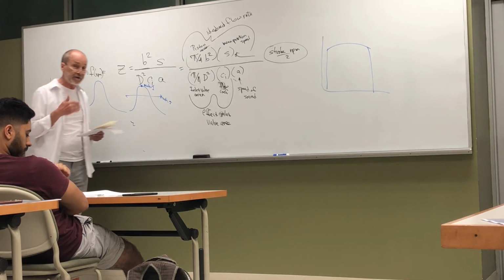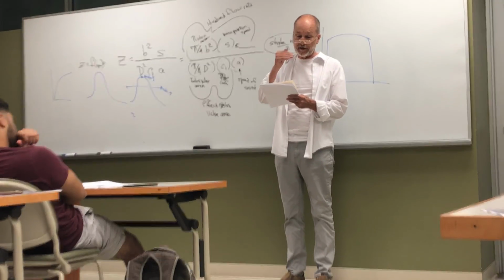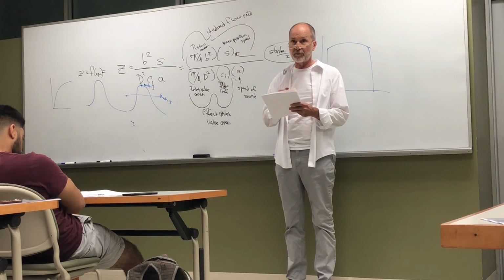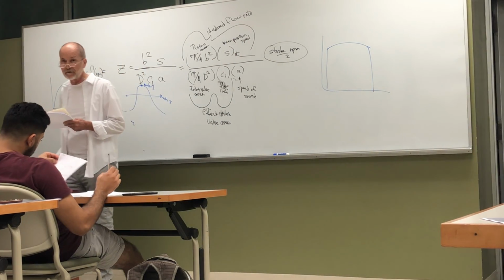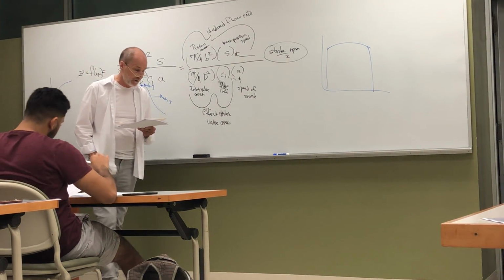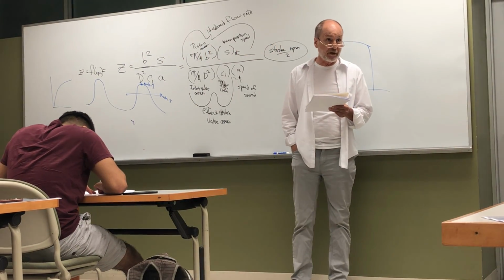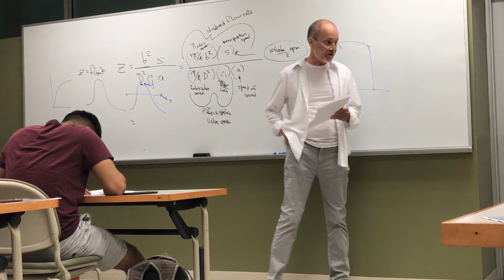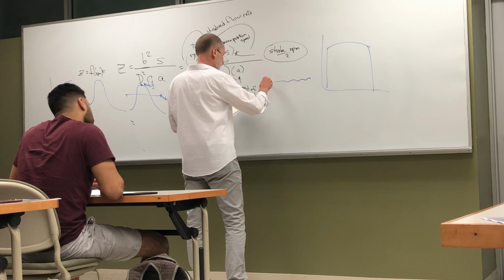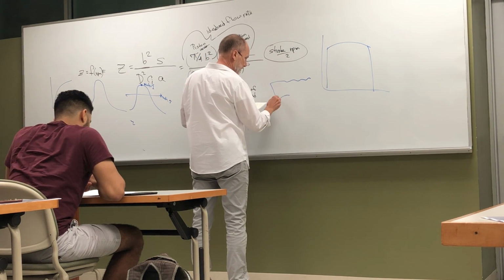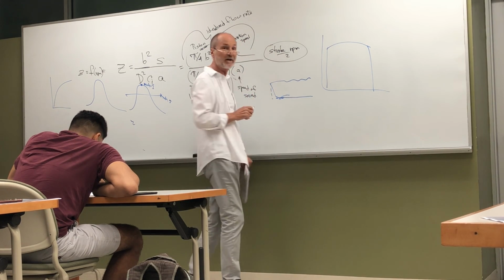So we've got three different operating conditions as far as manifold pressure, and we have Mach index 0.2, 0.4, 0.6, and 0.8. Let's go to wide open throttle in the middle. The first one's 0.2. All the way at the top, you can look at the loop, see how the pumping loop nearly has corners on it. It comes down, here's the exhaust, and it's nearly like our idealized one.